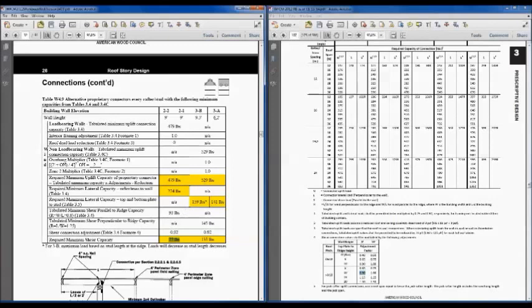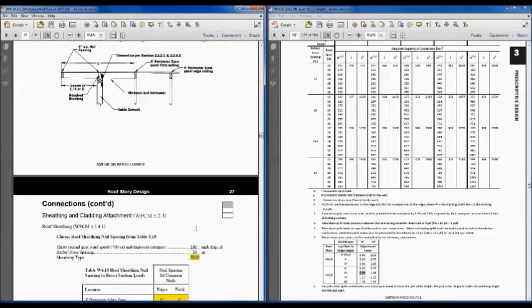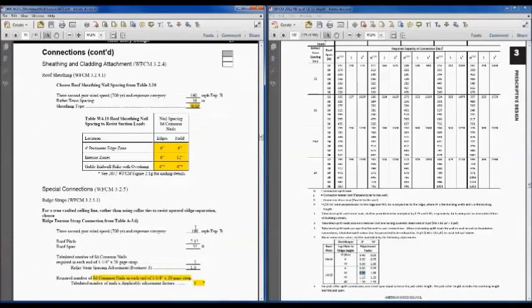Again, to save time, I'm going to skip over the gable end walls, but there are similar tables for your gable end walls. Table 3.5 allows you to get your lateral capacity, and then you just look at the other direction for your shear capacity. Your length to width adjustment in that case is 1.25. So that gets us through those connections for the rafters to the wall system.